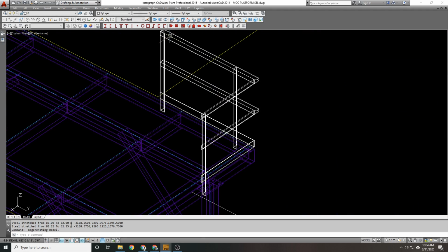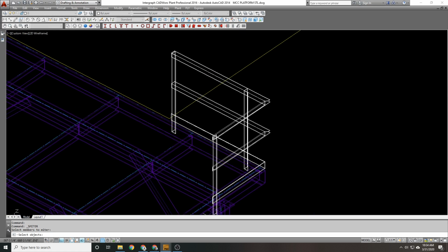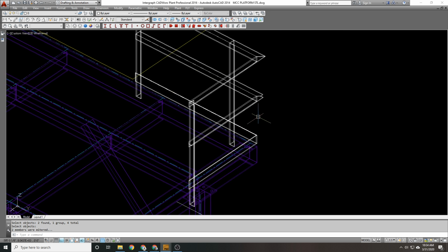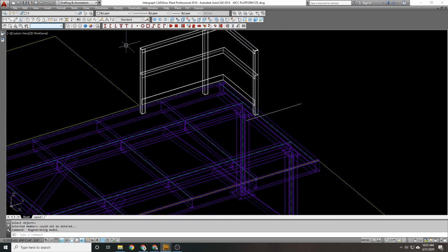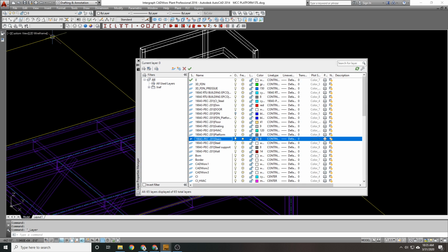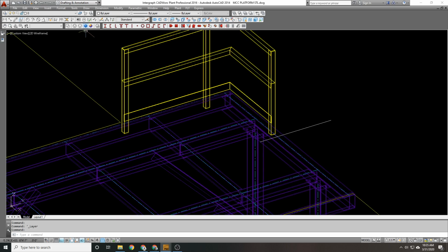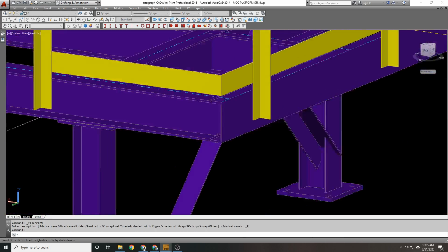Now I'm just going to miter these, and that'll reset the miter here, that overhang. When I do a miter with these two angles, it'll reset this, because now it's only applying a miter at the corner. Okay, these are all good. And I think that's good for that. Are these on the handrail layer still? Yeah, let me put the handrail layer back to yellow, which is what I had it before, so that I know I'm working with handrail. Okay, so it might be something more realistically like this.